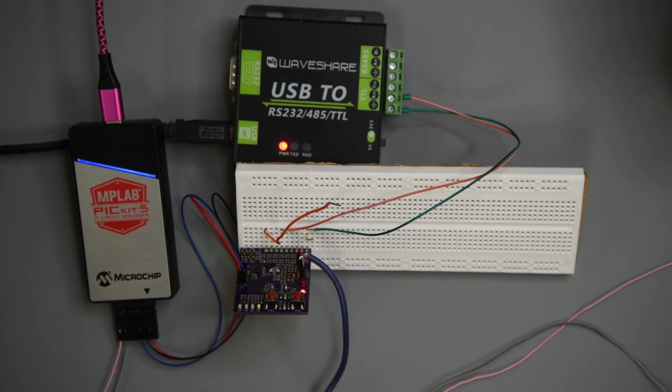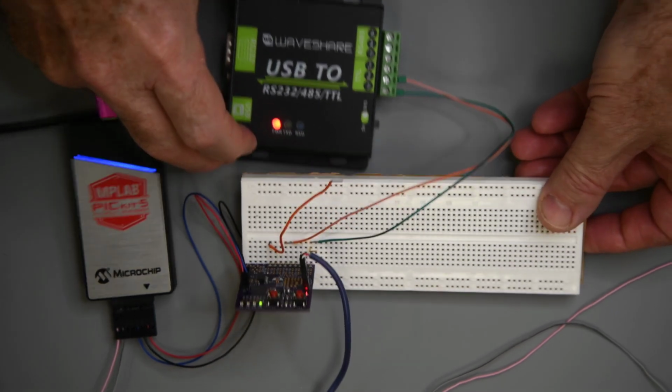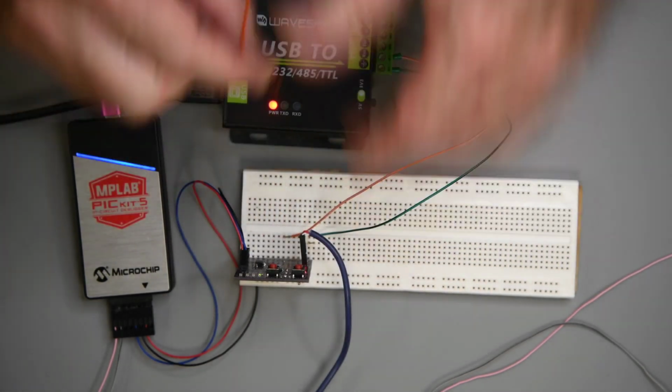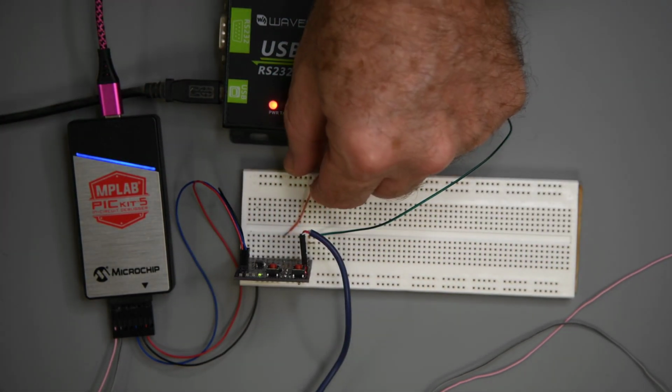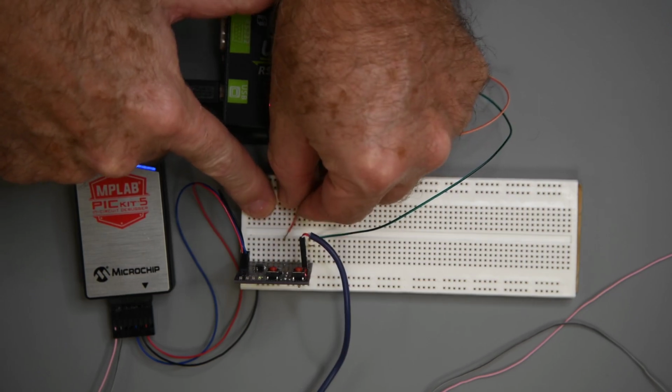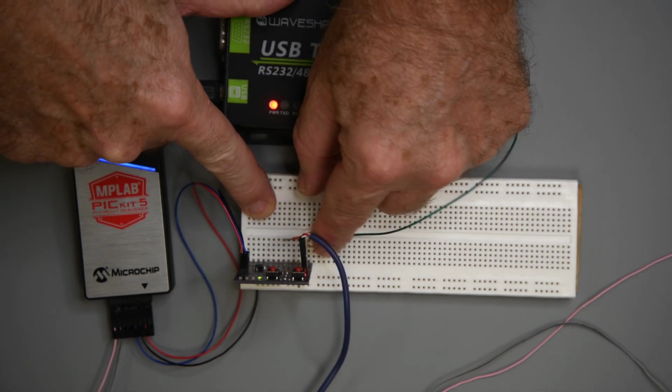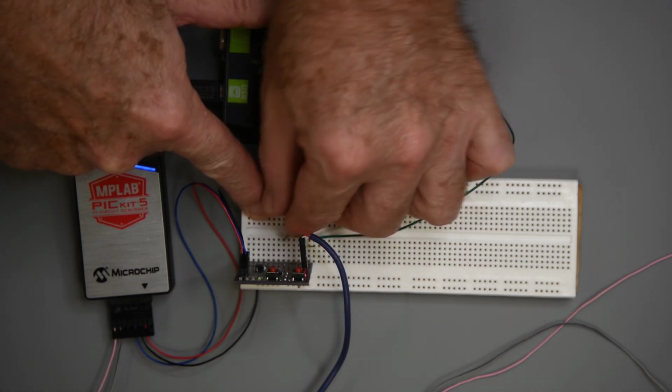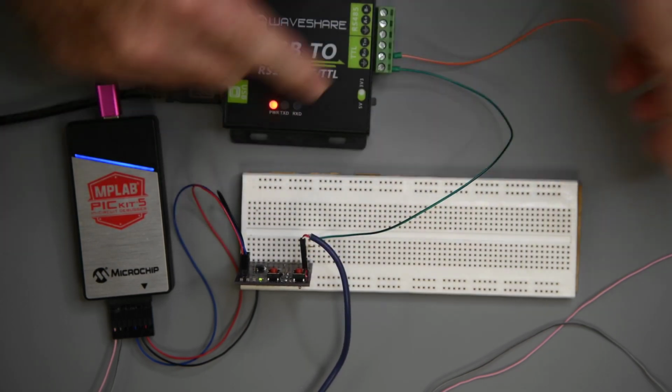But the Pickit 5 does have a serial port pop up when it's plugged in. And the pins are easy to access. Well, all I had to do was make myself a new cable. And as a bonus, I would expect the signal levels to track what the VCC target voltage is set at. So let's see if it works.